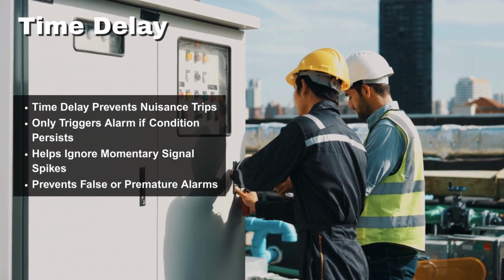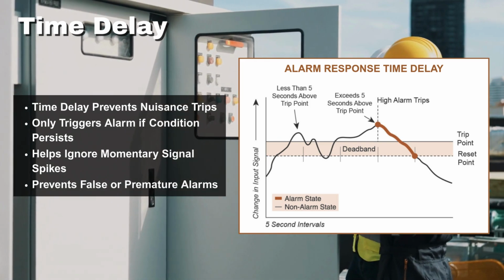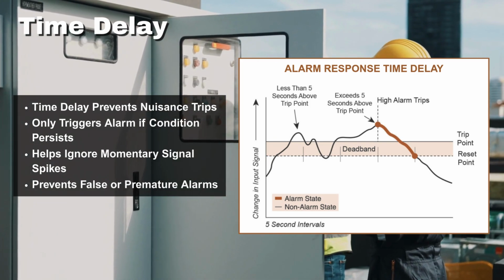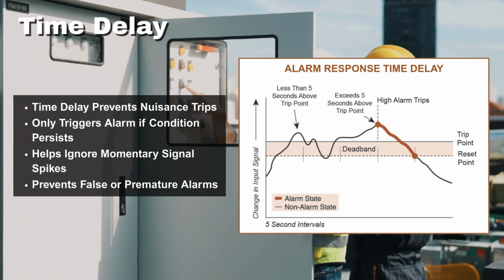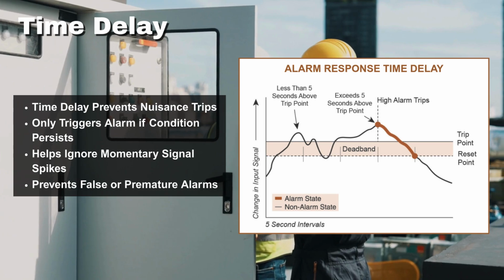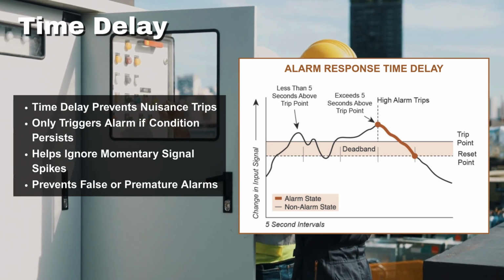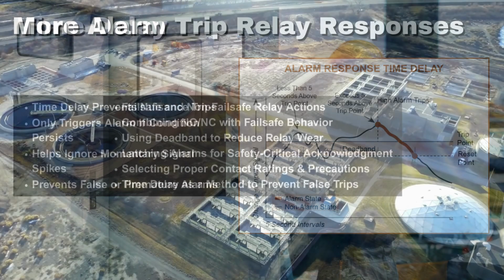Sometimes a quick spike in a signal doesn't mean something's wrong. That's where time delay comes in. With some alarm trips, you can set a delay, so the alarm only triggers if the signal stays above the trip point for a set amount of time. It's a simple way to avoid nuisance alarms and make sure you're only alerted when it matters.